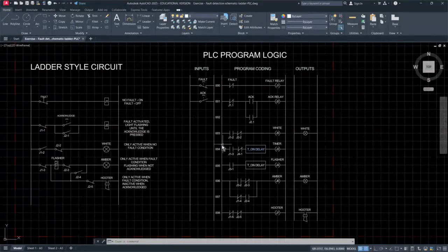And then the next 2 runs, which are run 4 and 5, I've got this T on delay, timer on delay. This is basically because in PLCs, flasher is a function. It's not something external, it's something internal. Some PLC programming languages would let you program it using Visual Basic or some other language, and you can just program that flasher with no extra elements. Just say little box there, flasher, and turn on and off every whatever number of seconds or milliseconds. It's as simple as this.